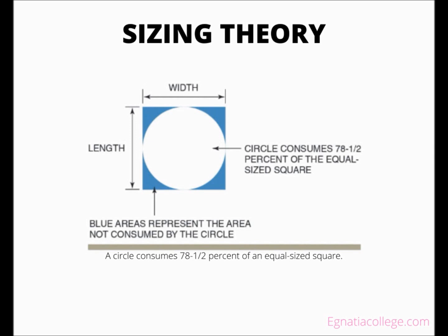Most residential fixtures have a hot and cold water supply, and the faucet type is often the determining factor of water flow. Codebooks will list the hot and cold values separately, but allow a deduction of the WSFU value when a fixture has hot and cold water supplied.